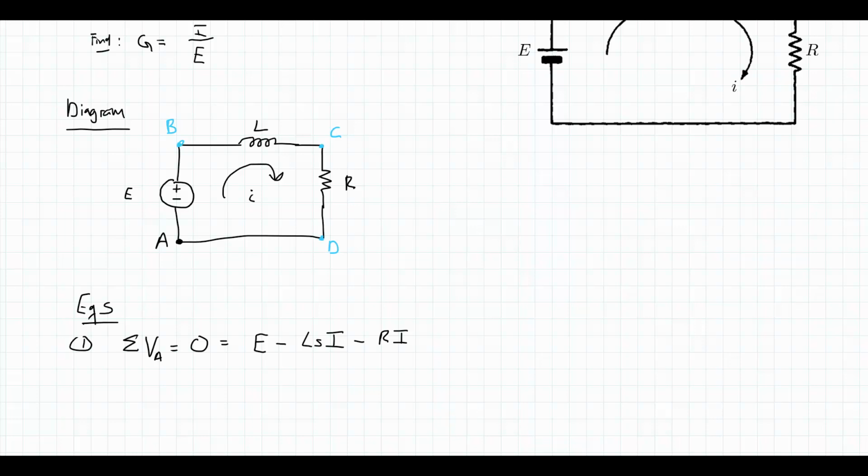So yeah, quick recap. From A to B, I went negative to positive through a voltage source. That got added positive E, which is a function of, well, here, frequency. From B to C, a voltage drop across the inductor because I am going with the current through that element. From C to A, going with the current across the resistor R, so a voltage drop.